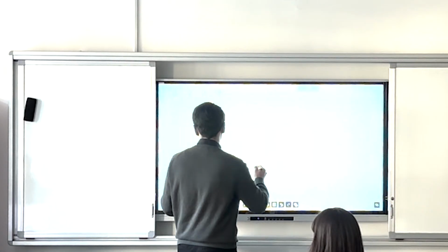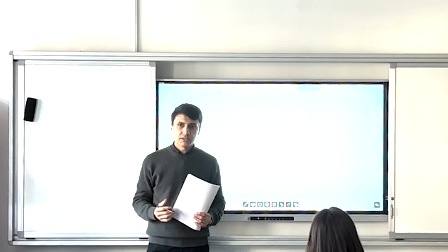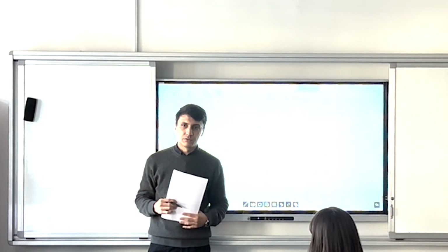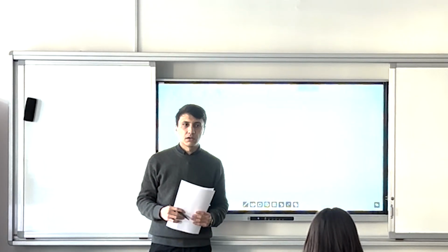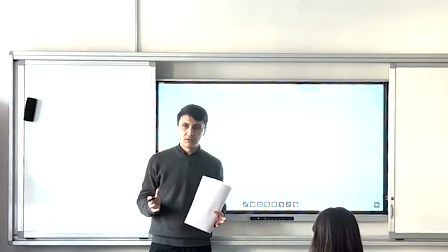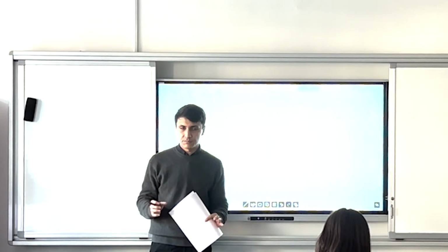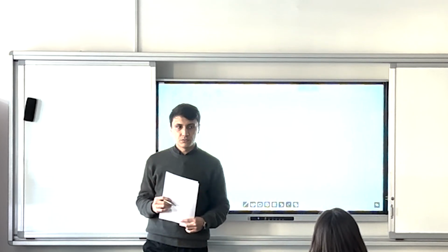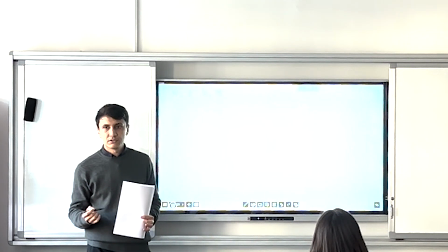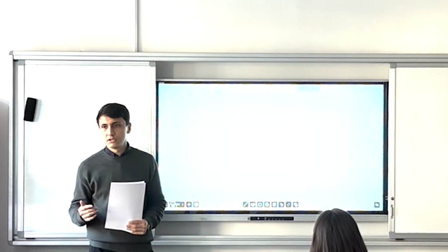So our exercise is to find the maximum yielding bending moment of the section, of the beam. We need to find how much bending moment the certain section can resist before the bottom steel rebar will yield. Yield means it will reach its yielding capacity, which is given in the Eurocode.